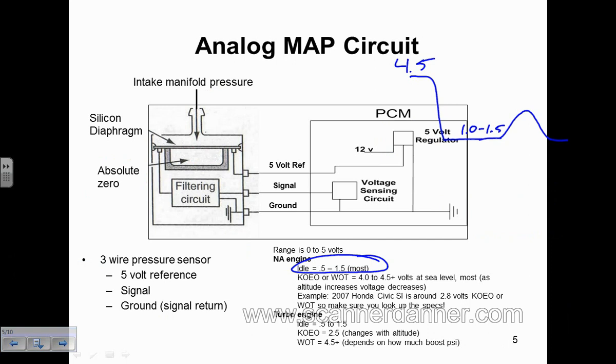If you want to check both extreme ranges of the MAP sensor, which would be idle and wide open throttle, right? Idle would be the low extreme, and wide open throttle would be the high end. We want to check both, just like a TPS, where you check it at idle, check it at wide open throttle, do a sweep test. How do you do that on a MAP? We don't need to snap it to the floor and hold it at wide open throttle and throw a connecting rod through the oil pan. What do you do? Turn the engine off. Turn the key back on. What's your MAP voltage? Same as it's going to be at wide open throttle. So again, this is a fundamental that you'll develop once you understand how it operates and what it should be doing, then you can do those kinds of tests.